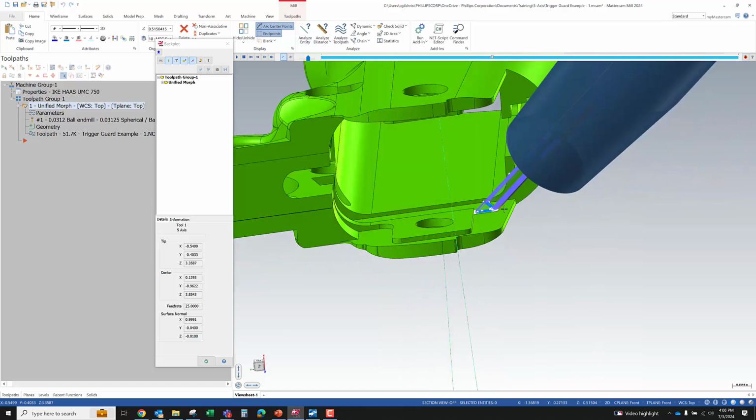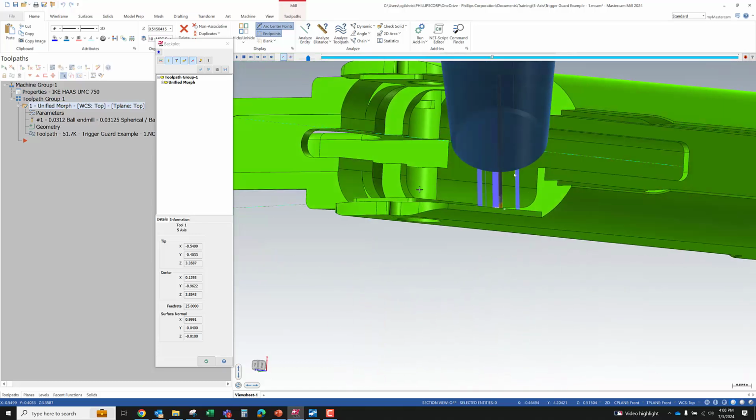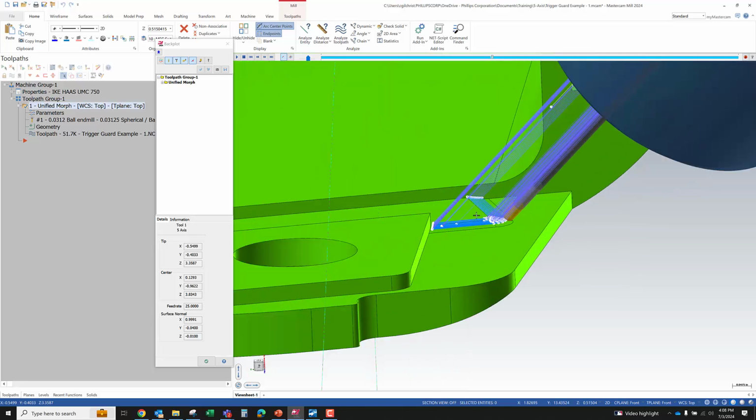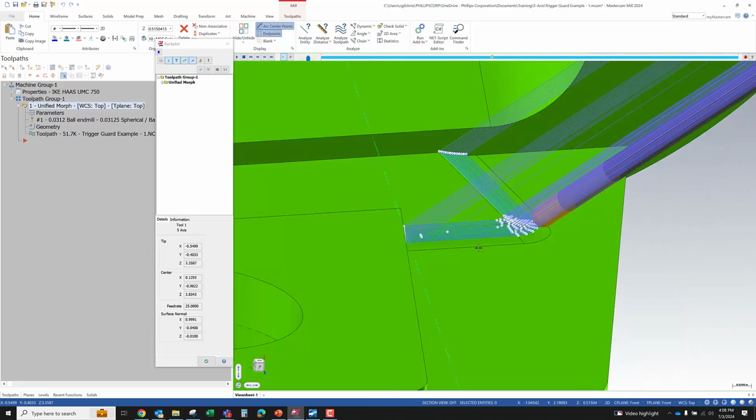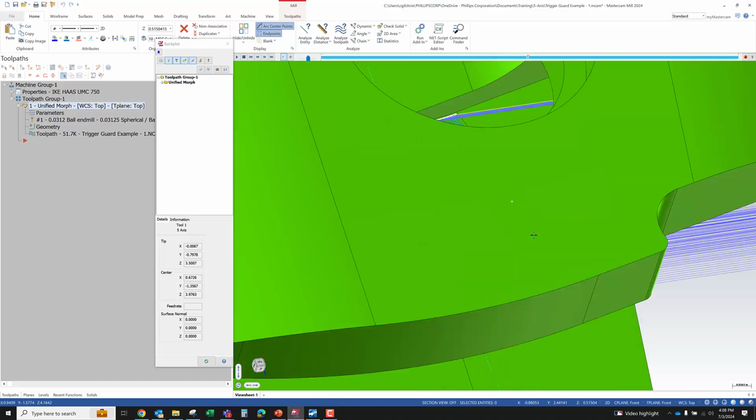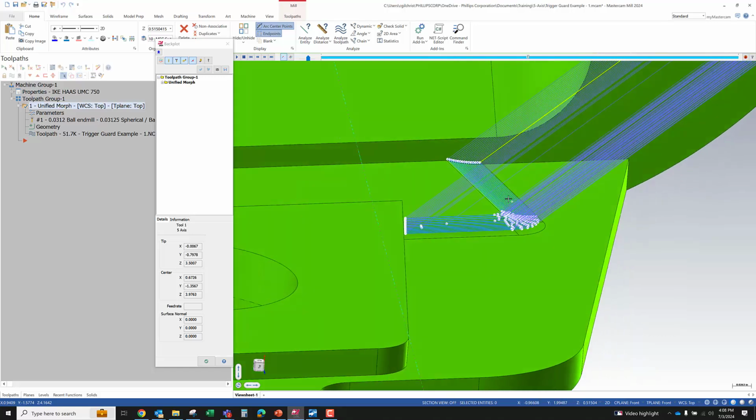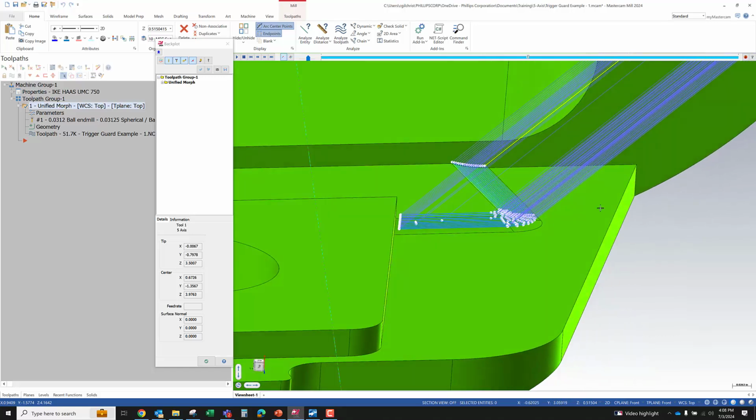Now, we could tilt this, we could do all kinds of things, but it's a great little example of an area where driving this with kind of traditional tool paths is not working so great. And maybe you need to do something over here to clean it up because you're going to use a little wheel cutter and that's going to leave a little chunk of material in there.